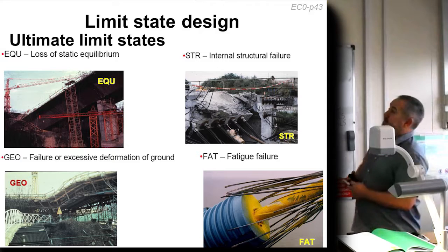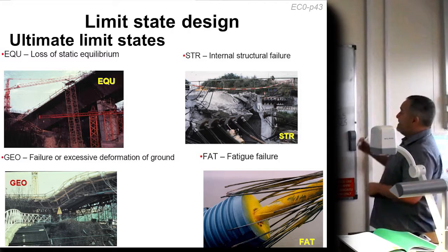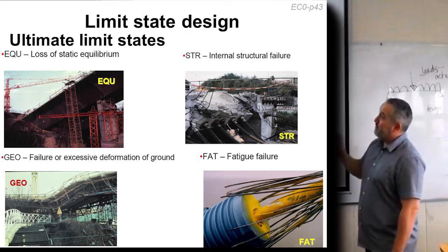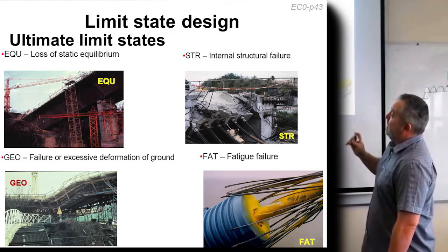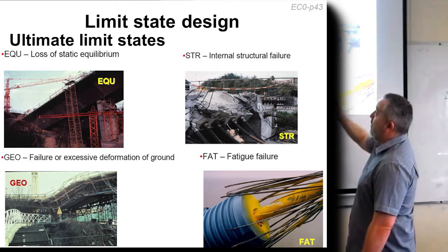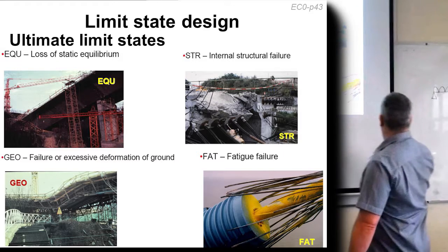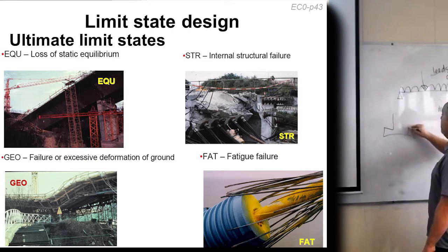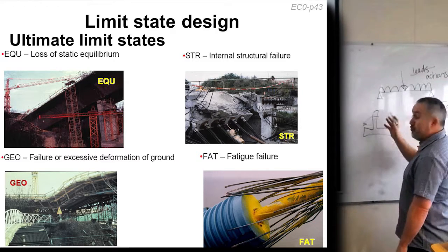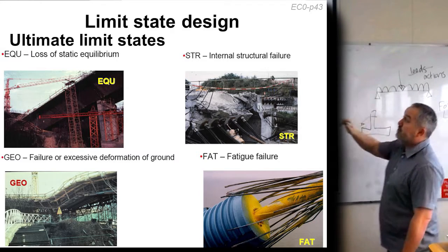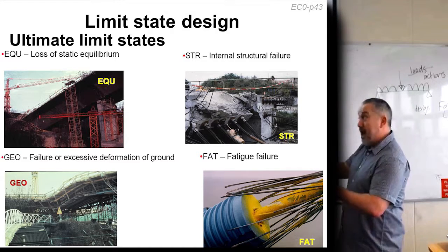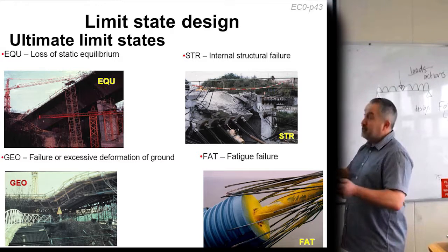For example, if we looked at ultimate limit state, that's split into 4 different categories. You've got your EQU, whenever you're looking at something in terms of equilibrium. So if you were designing a retaining wall and you were wondering whether it is going to rotate around, then you would use the factors of safety in the equilibrium area, and you'll find that there's a table just for that.